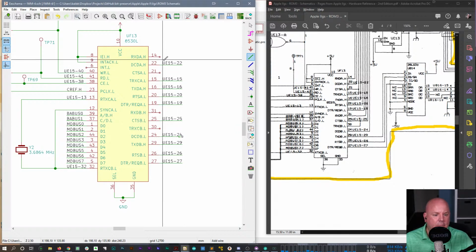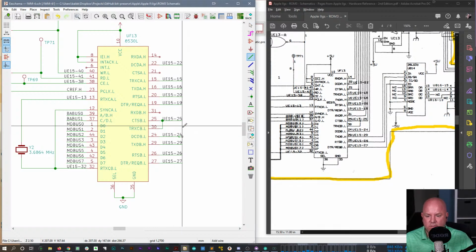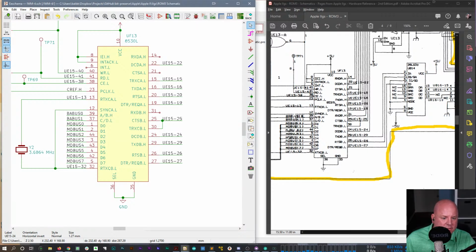Okay, so now pin 14 doesn't have a label. Okay, the rest of these don't, but this connects to this one. So let's undo that. W for wire, connect to here. And let's see, 31 connects up somewhere, so we've got to go find that one. All right, so let's save this for now. And then let's go find, oh, this one's not connected because it's too far over. Nope, just didn't draw it far enough. Okay, so let's go find where 31 gets connected.